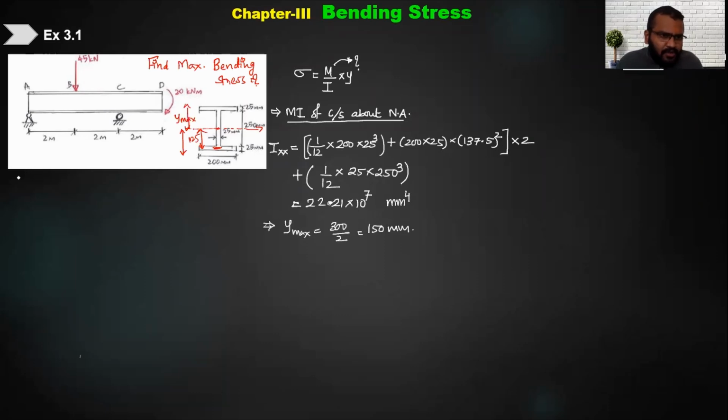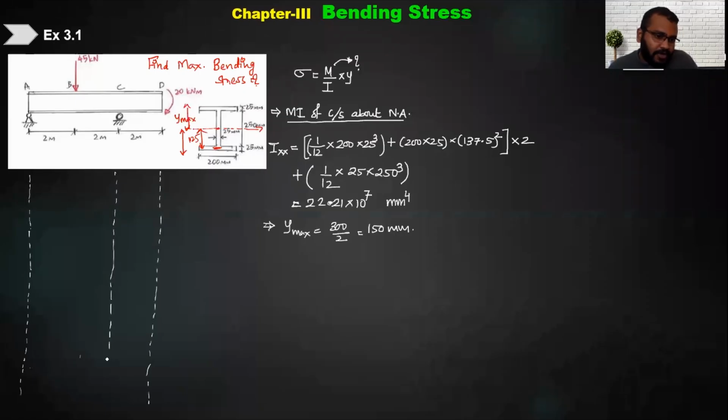And I don't think we need to do the calculation right now. We can directly draw the SFD and BMD looking at the diagram. Or else if you want, you can continue with calculating and give me the values. Okay, since it is the first question, we will not do it directly. Let's calculate it. We will do the SFD and BMD part here. This is my point C. I am drawing dotted lines for point C. And this is for the point.